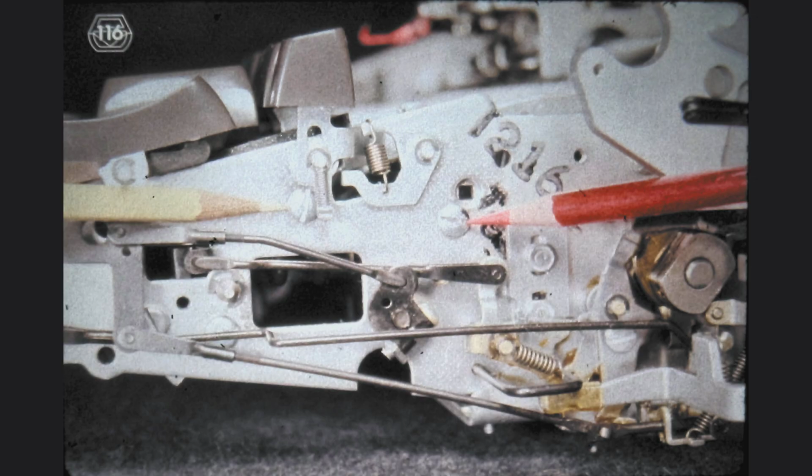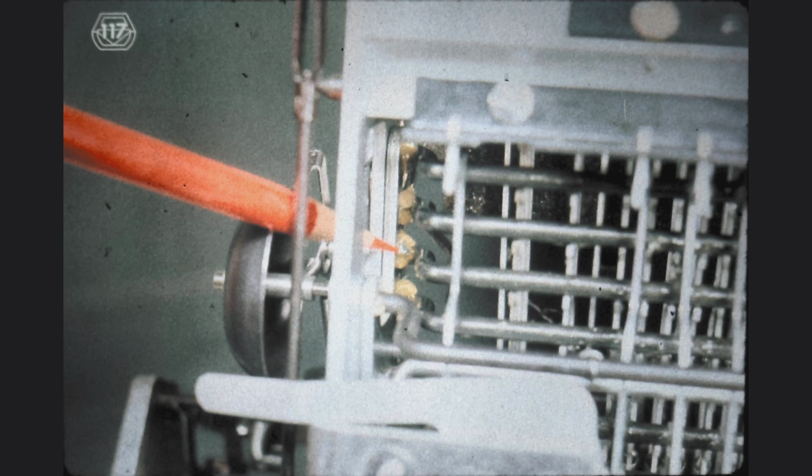One very frequent complaint with the Selectric typewriters is that they produce a lot of noise during their operation. Keyboard noise can be substantially reduced through the application of a film of grease along the full length of the character selector bails. However, do not apply this film of grease along the cycle bails. Always be sure to apply lubricant to the pivot points of the bails at the indicated points.